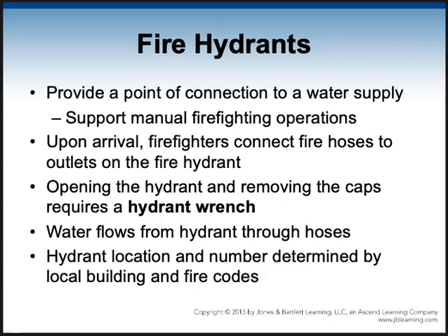You apply the hose, thread the hose onto the hydrant, and then you're going to open it with a hydrant wrench. You never use a pipe wrench. It destroys the nuts. So I'm going to show you a hydrant wrench here in a second. So the water's going to flow from the hydrant through the hoses into the engine, and then the engineer will control the amount of pressure and the different hoses that it will go to for suppressing the fire.